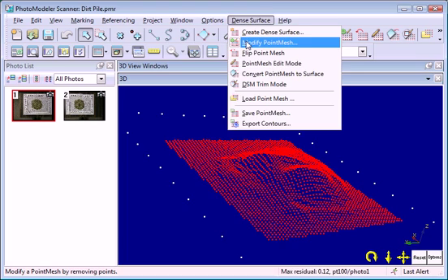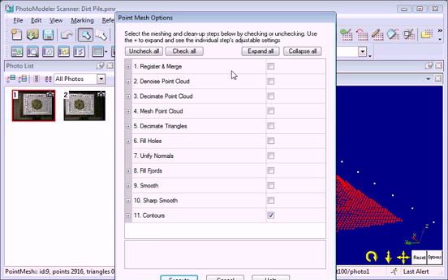These first steps deal with the point data and are covered in the previous tutorial. Step 4 uses the existing point data to create a triangulated mesh. These remaining steps adjust the triangulation in various ways. You can run each step independently or have them run all at once. For example, we could mesh, fill holes, unify normals, but leave off the other settings.